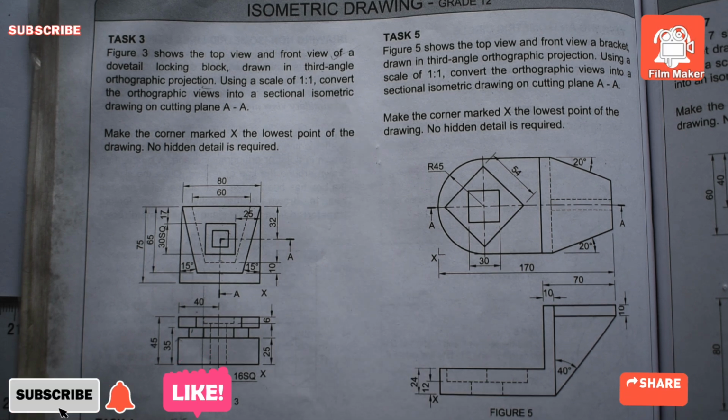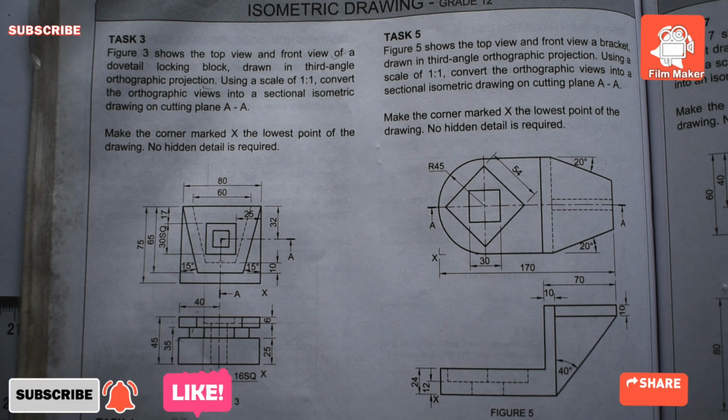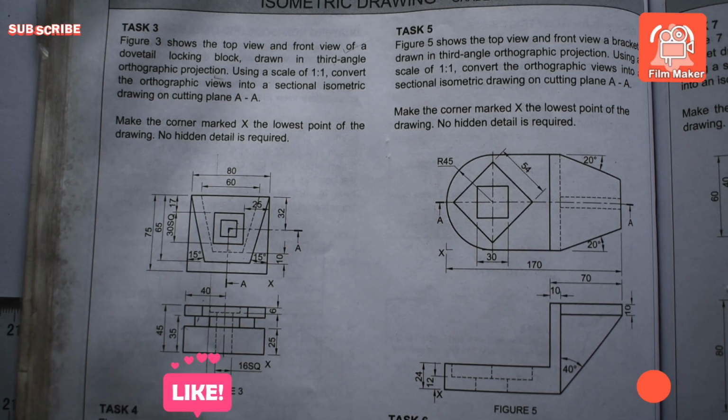So use a scale of 1:1 to convert the orthographic views into a sectional isometric drawing on the cutting plane AA. So what we are doing today is the isometric drawing in sectioning. Understand? So make the corner marked X the lowest point of the drawing. No hidden details are required. You understand? So let us start.